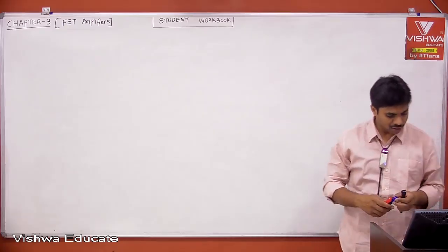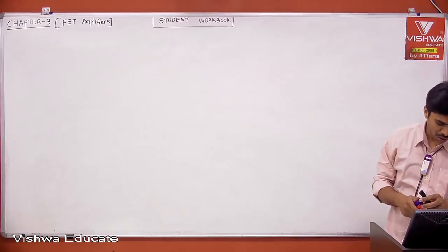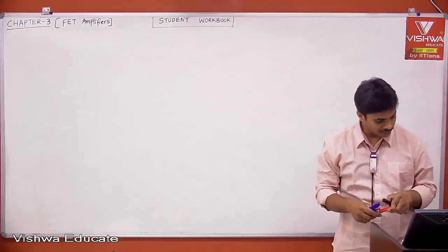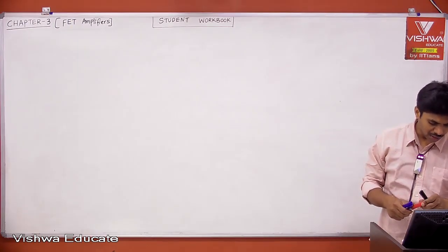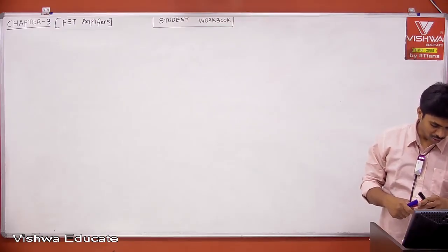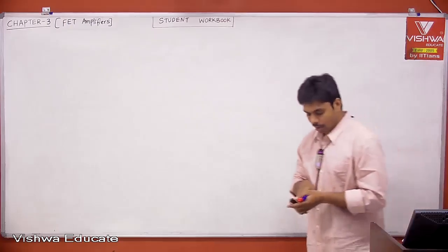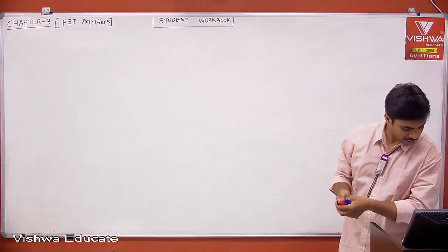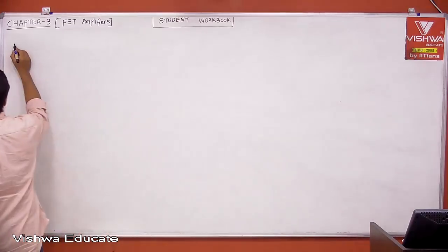The small signal resistance dVb by dId in kilo ohm offered by N channel MOSFET shown in figure below at a bias point of 2 volt and device transconductance parameter mu n Cox W by L 40 microampere per volt square. Threshold voltage is 1 volt. Neglect body effect and channel length modulation. Therefore, indirectly asking us to take ideal models only. Okay. Now, therefore, the problem is MOSFET is given and asking for the resistance. Okay. Problem number 3.